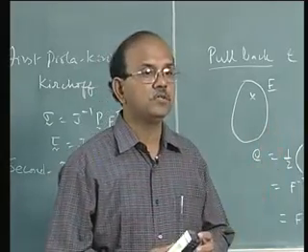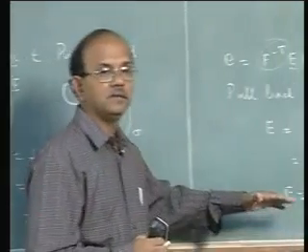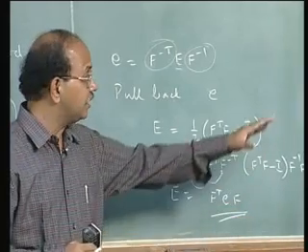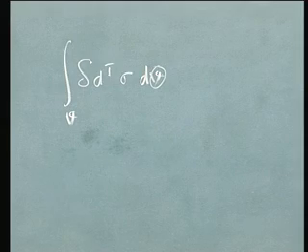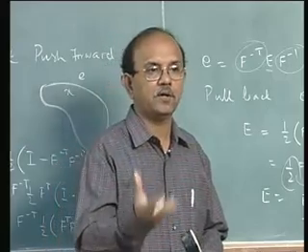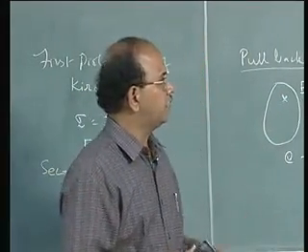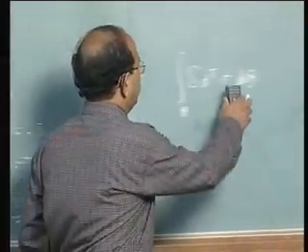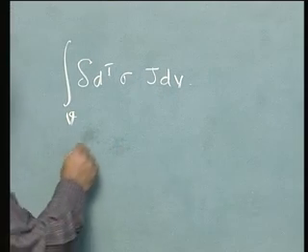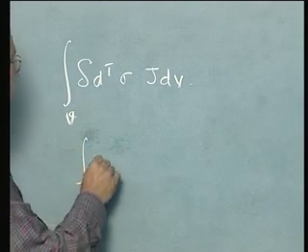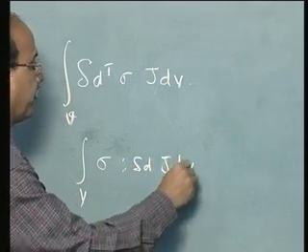When I convert that to dV capital V, that will be the pullback transformation, such that you will see that the stress power is not affected by varying the coordinate system, whether it's the reference coordinate or the current coordinate system. Right? So the first step obviously is to replace this d small v by J d capital V. This in vector notation is also written as sigma double dot delta d J dV.